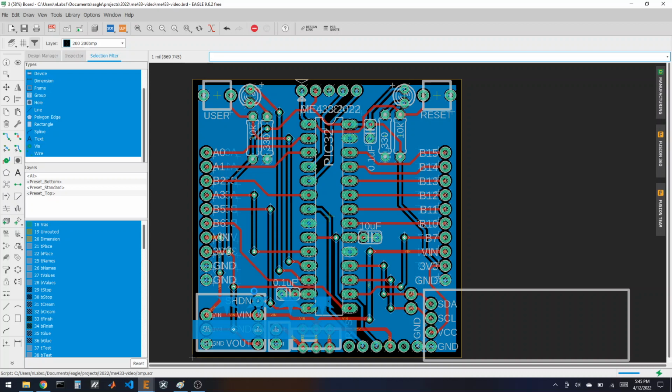But in this way, rather than put this in this layer, we could put this in any layer, and this is how you could do PCB art. So you would draw your art in some other art-based program and then kind of import it to Eagle. Unless you want to figure out how to do art in Eagle.